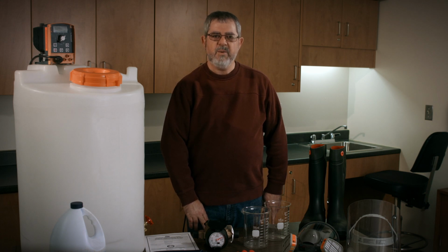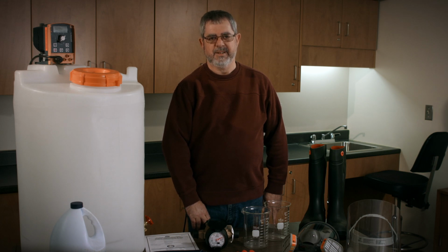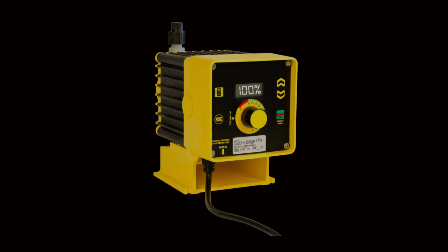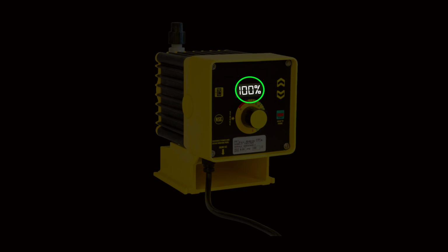Remember, the only time that we should change the concentration of the disinfection solution is when we are establishing or adjusting the required disinfectant concentration strength as required by the chlorine metering pump injection rate capabilities. This will occur when we are setting up a new system or when changes to our source water quality change the chlorine demand and we have reached the maximum or minimum limit of the metering pump while requiring further adjustment.